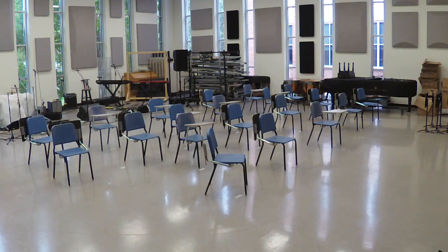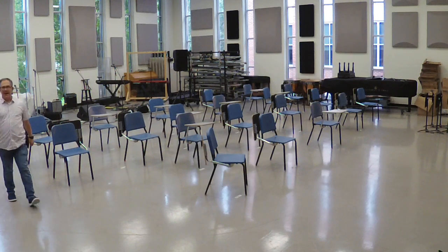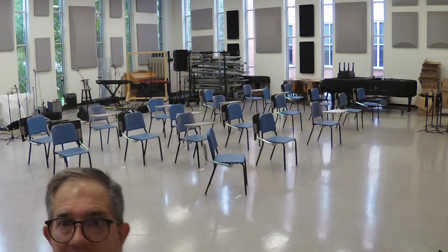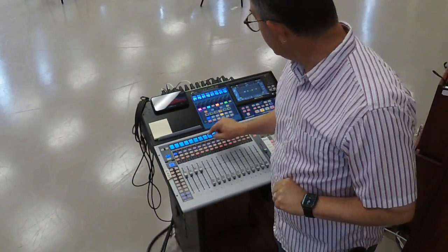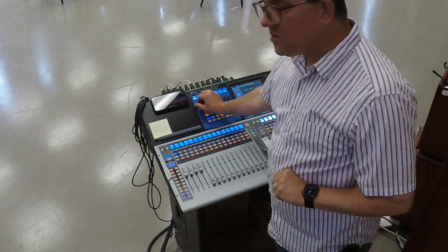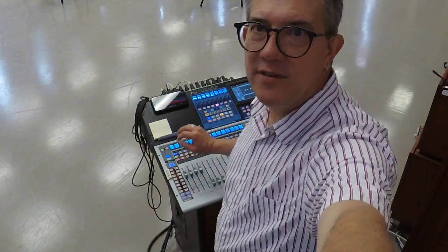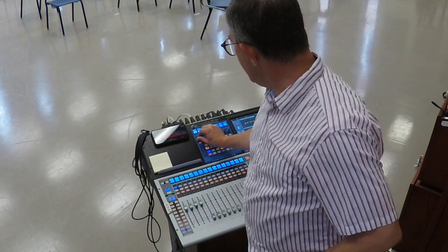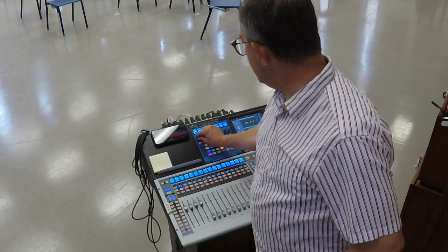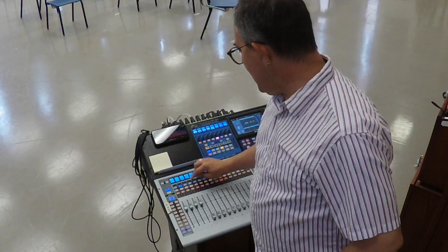Because of where I have the gain set on these, I actually have more gain than I need. So now that I've set and worked the system out from a frequency standpoint, I'm just going to go back to these channels and turn the gain back to a reasonable level. For instance, where I'm at 40 dB of gain, I probably don't need 40 dB of gain. 30, 32 is probably fine. And now I have rung this system out so it will be better behaved.